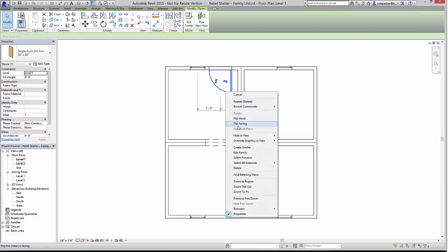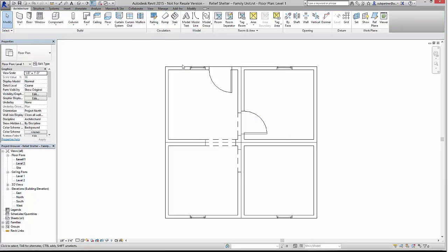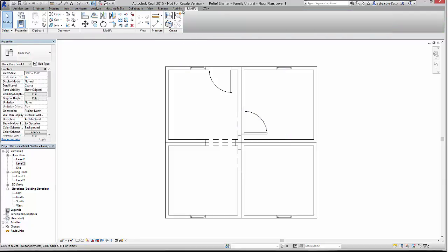When you try to place the first door, you may not be able to select a point in line with the existing opening. You can, however, quickly place the door and then align the opening with it using the Align tool.